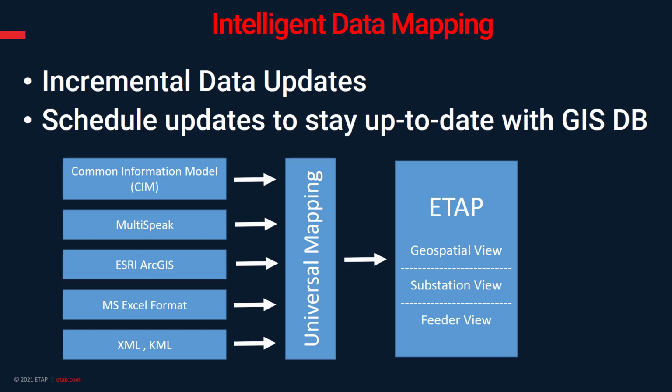And essentially, as the GIS team updates the electrical information and all the information, then ETAP automatically connects to the GIS database and performs incremental data updates. So in this way, your ETAP model always remains up to date with the GIS database.